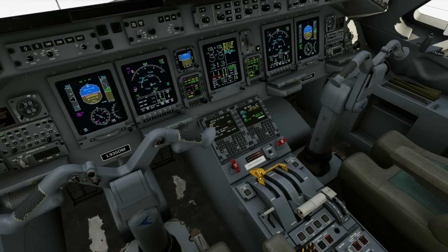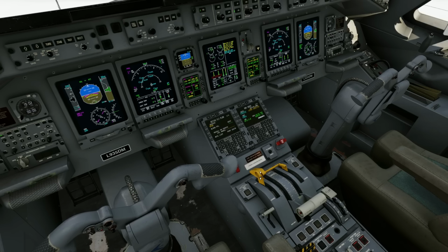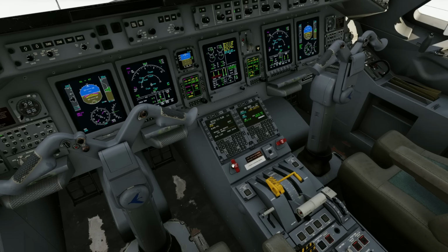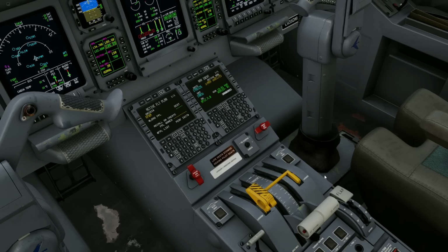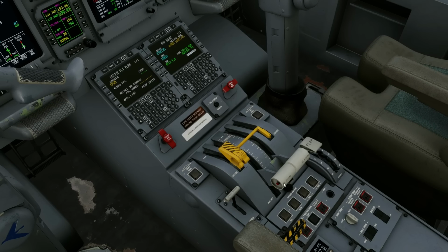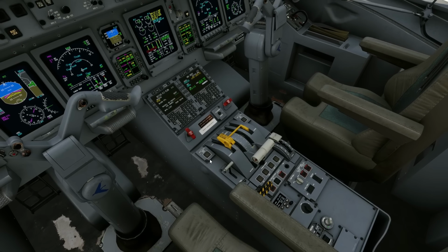To lock the Gust Lock, we take the yoke all the way back, slide the Gust Lock all the way back to the rear position, and then push and hold it forward. The yoke gets stored in the forward position, nose down. And so now I can release pressure on the yoke, and the yoke is now locked. All right. Actually, I should have done this with the Gust Lock released, so we'll go ahead and do one more for your viewing pleasure.